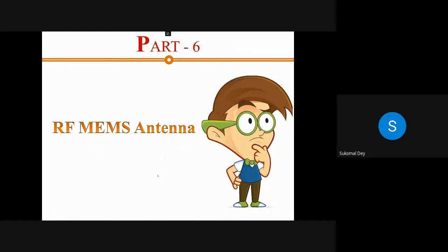It is well known that an antenna is developed in PCB technology. It is also developed in CMOS technology, but nice antennas were also developed in micromachining technology. But whenever you are using micromachining for the antenna, area plays a very important role. If you are making an antenna in a micromachining process, it is better to make it at a high frequency, because for a patch antenna, the patch size is a function of frequency.